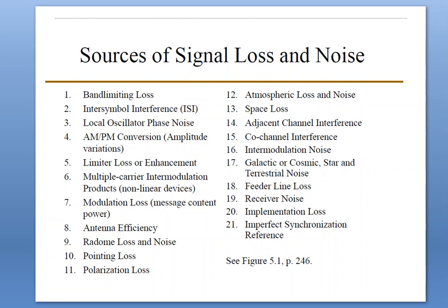It can be introduced in a variety of ways, such as accidental transmission, insufficient vertical and horizontal polarization discrimination, or radiation spillover from an antenna sidelobe. It can be brought about by another authorized user of the same spectrum. It is also one of the main reasons for co-channel interference.